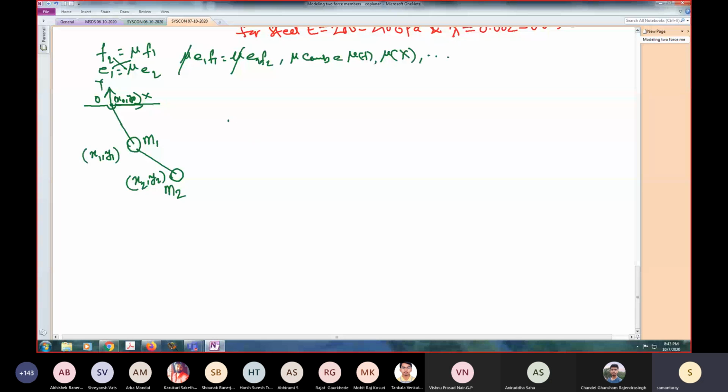I have one x0 dot, which is a source of flow equal to 0, it doesn't move, the pivot point. So you don't require inertia, you don't require a flow sensor. We have one y0 dot, exactly identical, source of flow equal to 0, no sensor required.